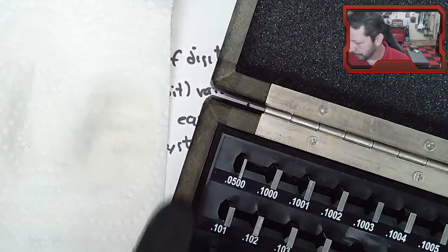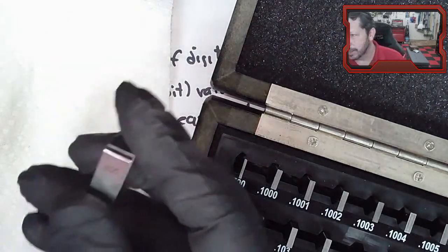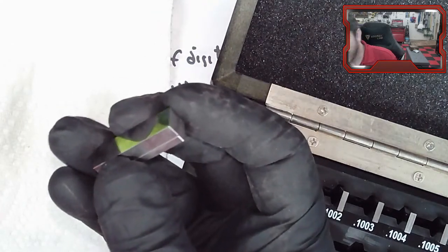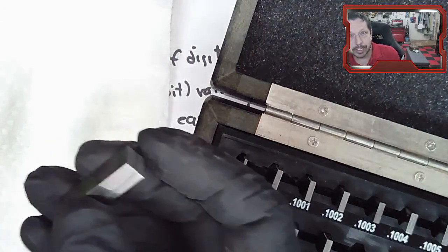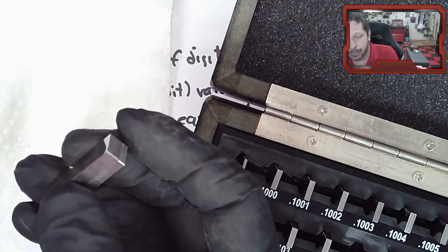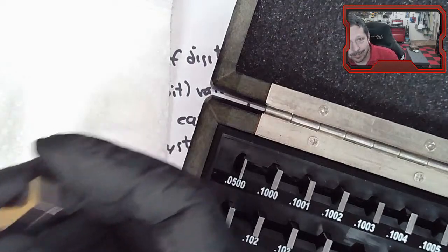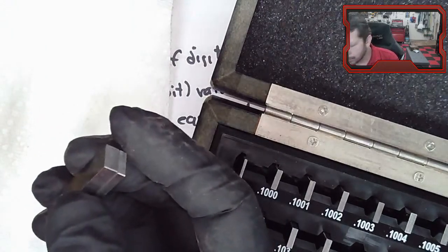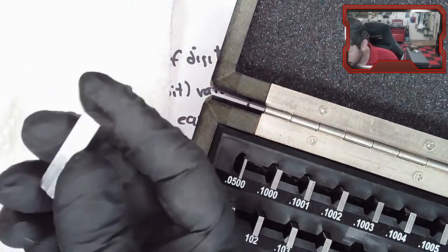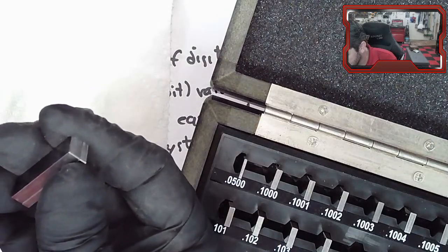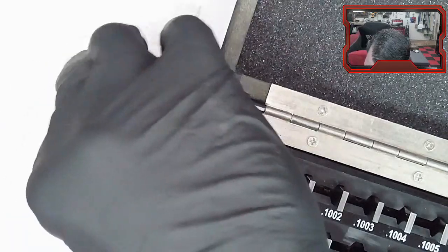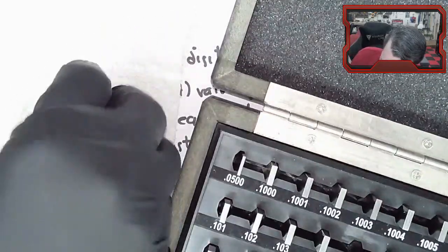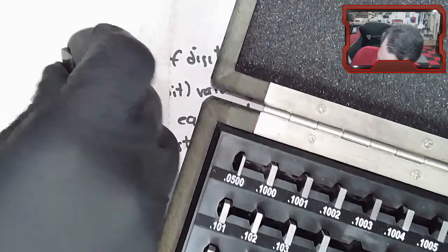So if you can create, with your whole set, a variety of specific lengths that are within millionths of an inch of what you intend for it to be. So you can use them in machining. You can use them to calibrate other tools or whatever. You don't want to leave them stuck together very long because they can become hard to take apart. But typically you twist them and they'll slide apart. So there they go, come apart.